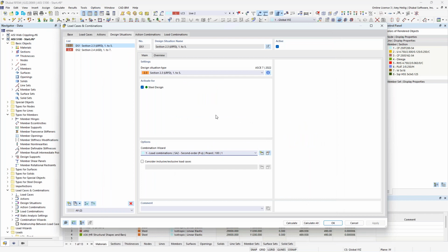The next topic is a consideration of initial imperfections set forth in section C1.1.2, and we have the ability to directly model the imperfections, but alternatively, the easier approach is probably just to apply notional loads. And these notional loads are usually applied to the members that are taking most of the gravity load, so we might think of our columns here, and it's applied to the top of the column to create the greatest destabilizing effect.